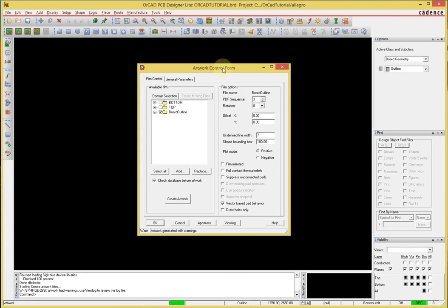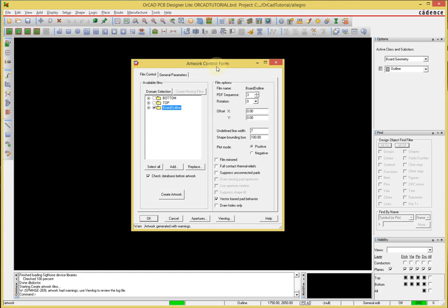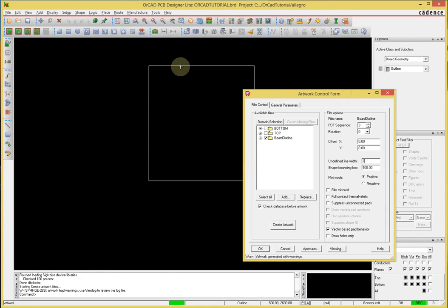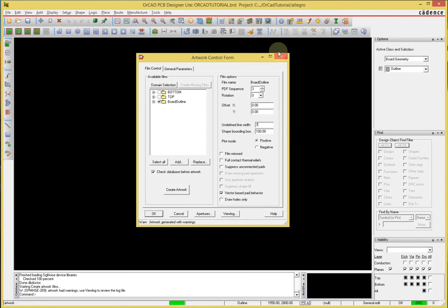You got the idea, hopefully, on how to generate those files. And you need to make sure that for any layers that have graphical elements that are not related to the generation of the PCB, that are just mainly graphics, that you have that undefined. So mainly the silkscreen layers and the board outline layer, because this is just to illustrate where the board outline is, but it doesn't mean that it's actually a renderable graphic component. So we have to force it to render by setting an undefined line width of non-zero value.